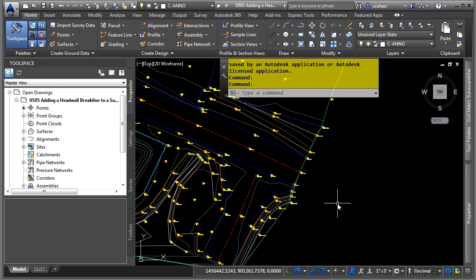Headwall breaklines are very useful when you only have either the top or bottom northing and easting elevation of a feature, and either a consistent elevation difference between the points or you've actually measured the distance at each vertex when you were in the field locating the objects. This depth would, in most cases, come from the surveyor's notes, of course.